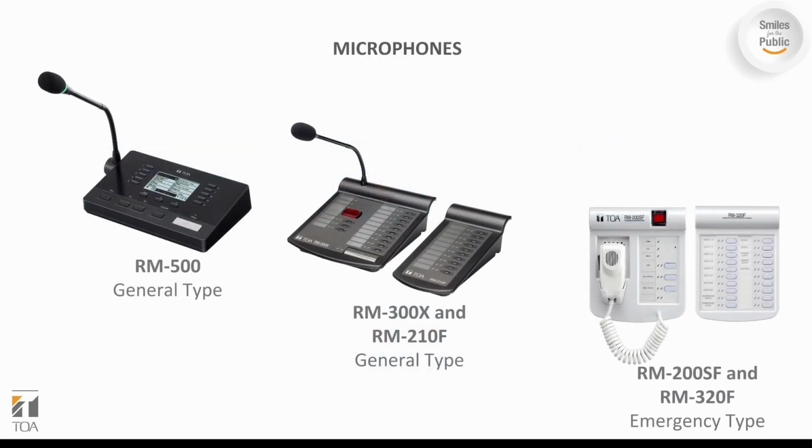Let's move on to the microphones. RM microphones are your basic input and control equipment for the VX3000. Depending on how they are programmed, they allow you to select zones, trigger events, initiate alarms, etc. Up to a combination of 8 RM mics can be connected to one frame. There are 2 subclasses of RM mics. These are the emergency type and the general type.